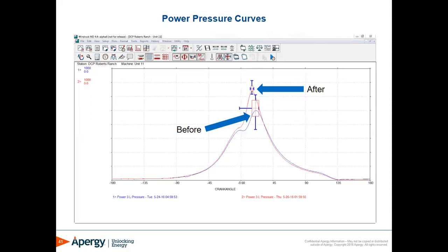Other than that, it's really just during your routine maintenance for the engine or compressor itself. We suggest opening up junction boxes, checking the wires, making sure there's no water leaking in or something like that, making sure all the terminal block connections are good and tight, just general maintenance that we'd suggest once or twice a year.